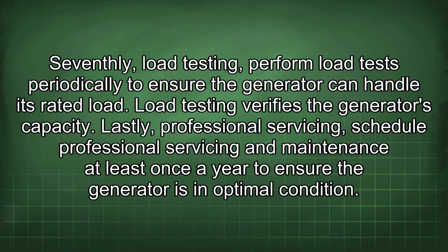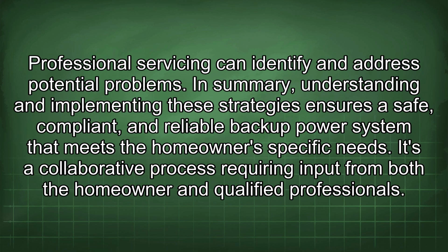Seventhly, load testing. Perform load tests periodically to ensure the generator can handle its rated load. Load testing verifies the generator's capacity. Lastly, professional servicing. Schedule professional servicing and maintenance at least once a year to ensure the generator is in optimal condition. Professional servicing can identify and address potential problems. In summary, understanding and implementing these strategies ensures a safe, compliant, and reliable backup power system that meets the homeowner's specific needs. It's a collaborative process requiring input from both the homeowner and qualified professionals.